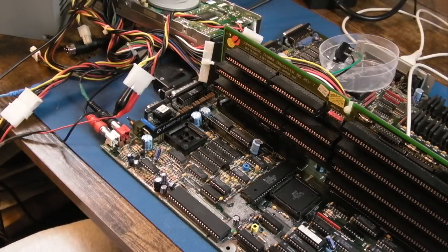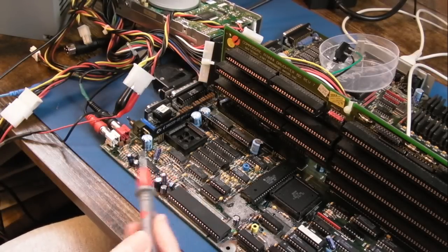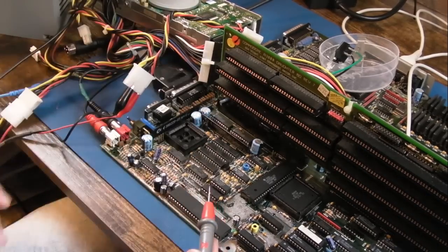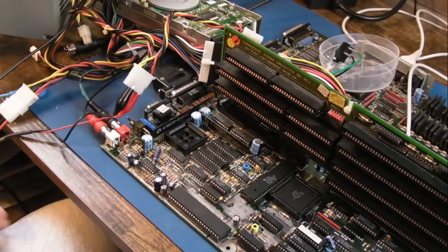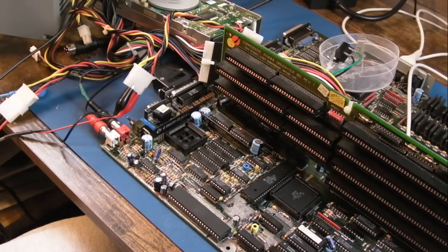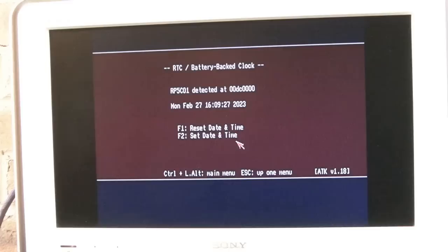So yeah, very pleased. The one thing I'm not sure about is where that trace was broken. I spent ages looking at the layout of the board that Chucky's publicised, trying to work out how those two resistors are joined, and I couldn't work it out. I just got lost trying to follow where the trace goes, because it probably goes through a couple of wires or something. My guess is it's probably a trace underneath this IC that was borked. So I just ultrasonicked that whole corner of the board.